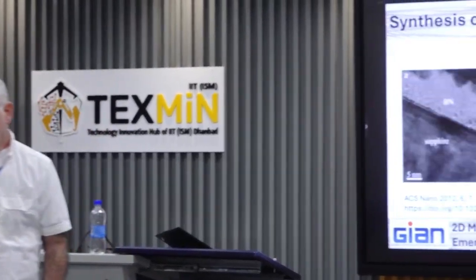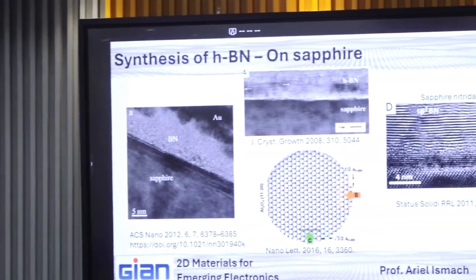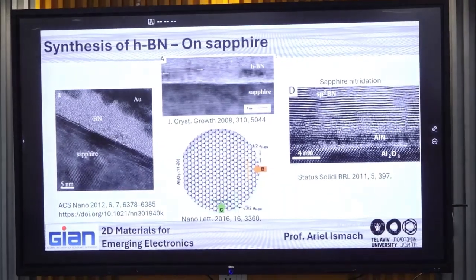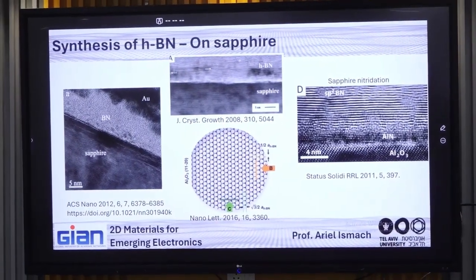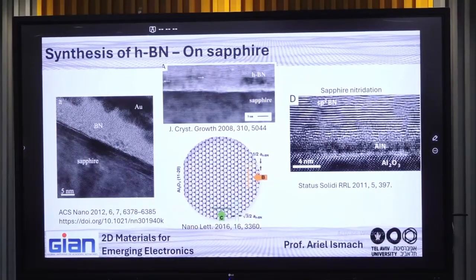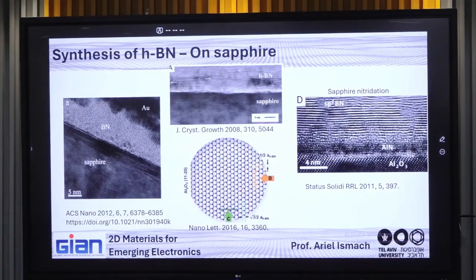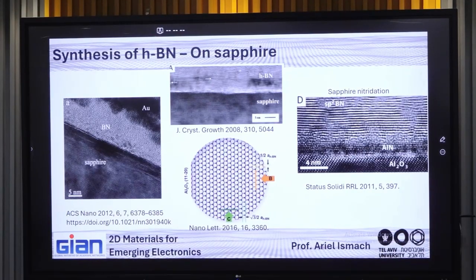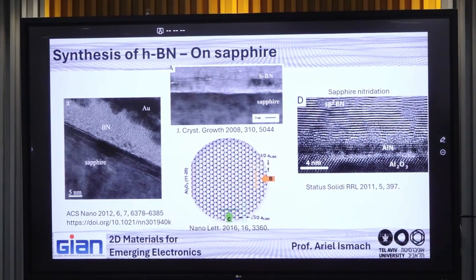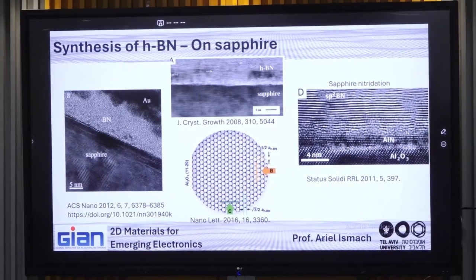And again, going back to the dielectrics, especially sapphire, the reason for using sapphire is that it is the magic kind of substrate. It is very stable, chemically and thermally, and it is used for epitaxial growth of other thin films, not only 2D, of course, gallium nitride and so on. So it's very resistant in this environment.